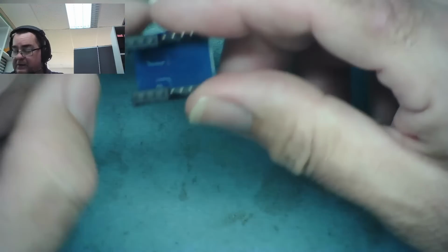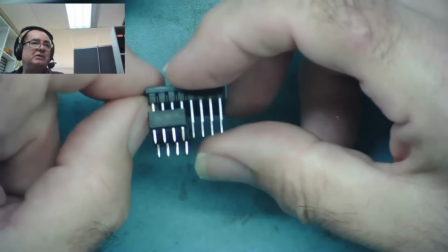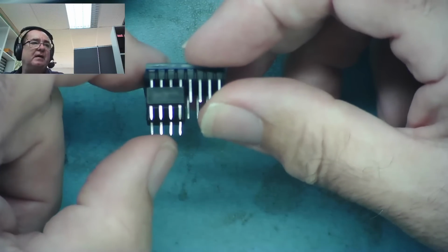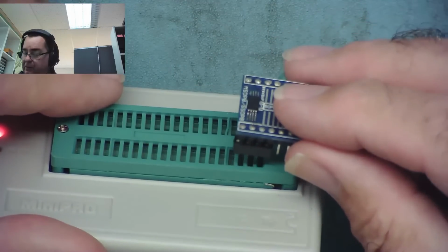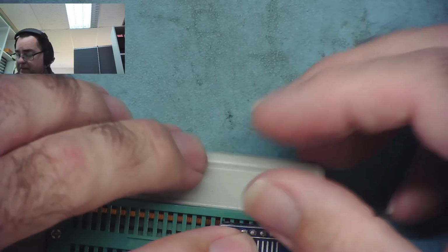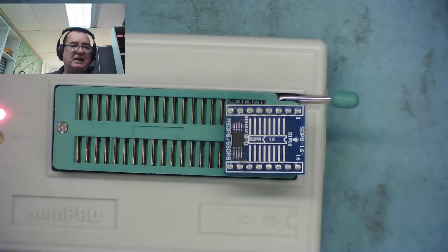So what I've done is, I thought, I'm going to get around that. I actually took an 8-pin IC socket and broke it in half. And I've extended the pins 5, 6, 7, 8, so I can now put it into the EPROM programmer for pins 1, 2, 3, 4. So I can get that into there. And I'm hoping now it'll read. Before it was just saying FFFF, and when I tried to program it with the guy's file, it just said error.